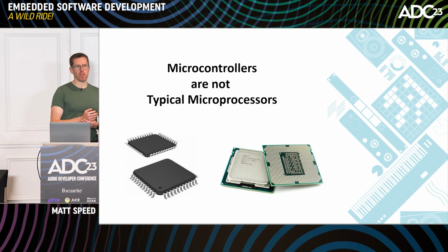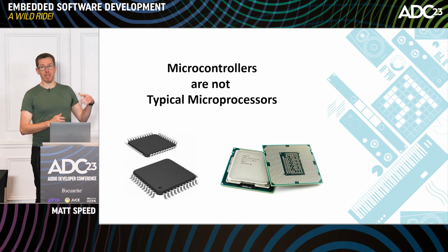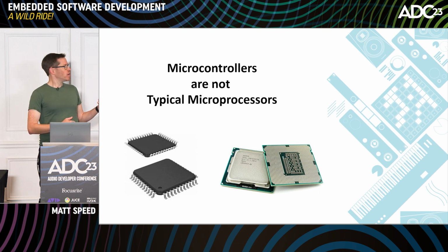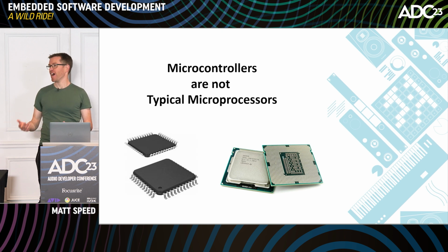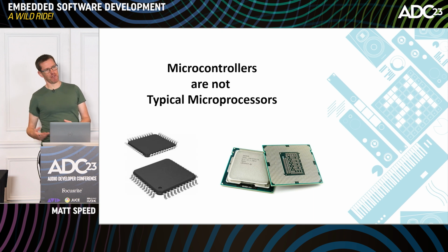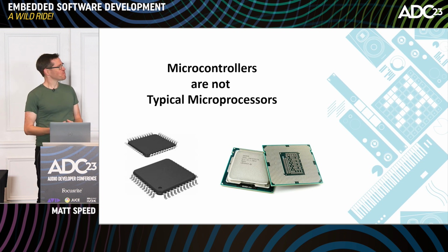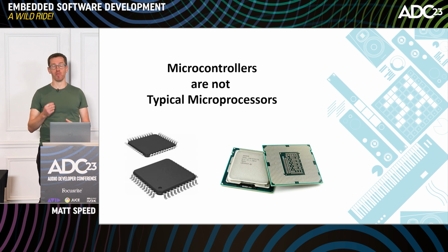Another reason microcontrollers can be particularly responsive is the immediacy of the memory. On a fancy microprocessor for a desktop, you'll be well aware you have layers of cache, like L1, L2, L3 cache, and this gets successively faster as you get closer to the core. We need cache really because the processors are so quick and so complex now that it's hard to keep them fed, so you need to have at least some memory that's fast and close to the core.